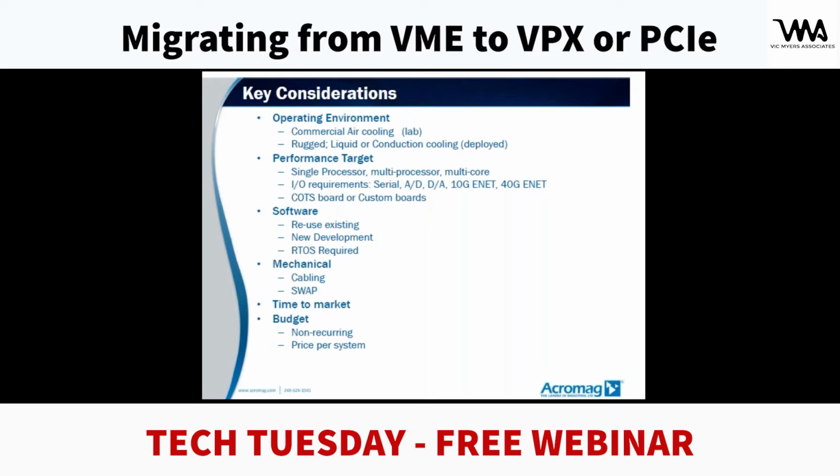And another key consideration is whether you'll require a real-time operating system. And typically, this will be very specific to the processor that you choose and what you're trying to achieve in the application. Mechanically, cabling, sometimes it's almost impossible to use existing cabling in the VME environment and trying to move to PCI Express server or the VPX. However, oftentimes you can make some type of boards that will concentrate I/O, and you will be able to use some of the existing cabling.